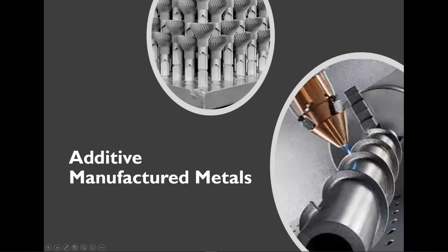All right, so just discussing a little bit on additively manufactured metals. They've only recently been implemented in the industrial world in the past 20 years or so, as compared to its counterpart, just the cast and die or subtractive manufacturing for the metals. And these metals are named so in additively manufactured due to their layer by layer addition, typically by the sintering or fusion of the powders.